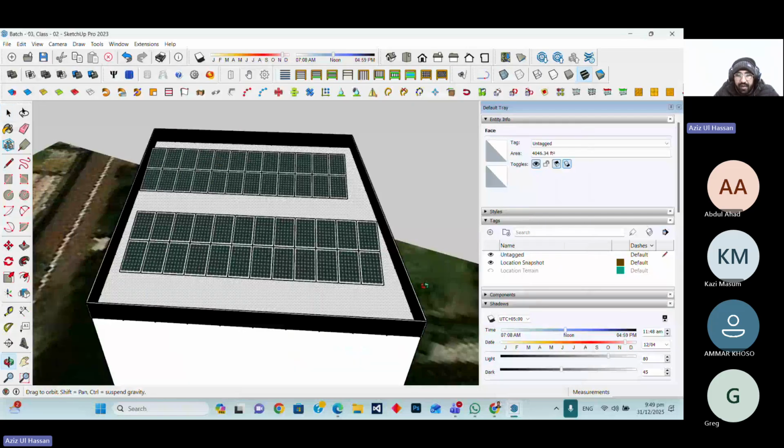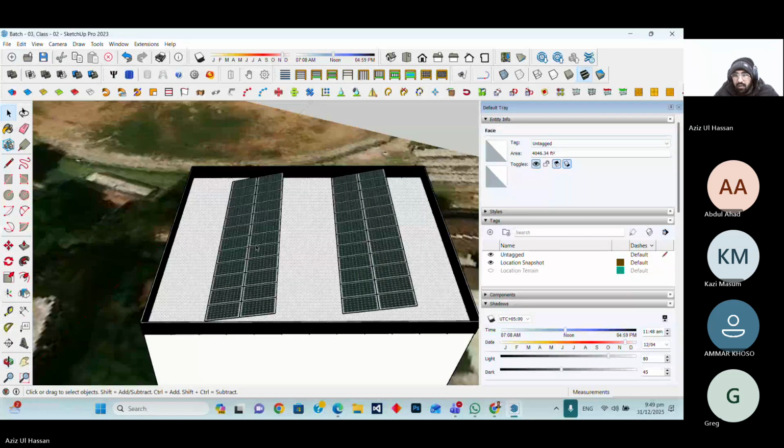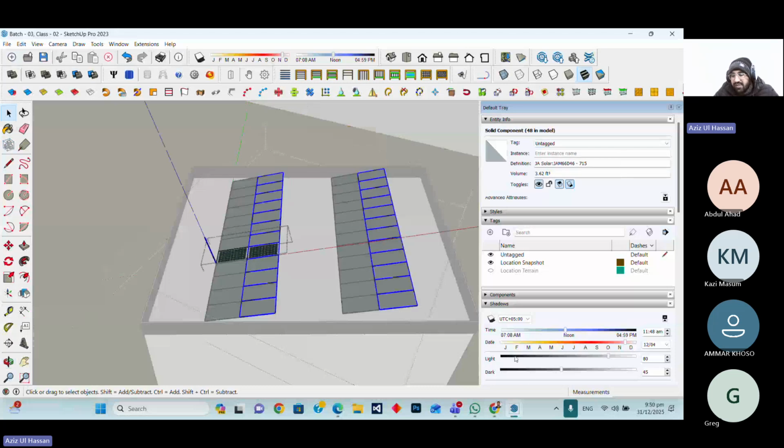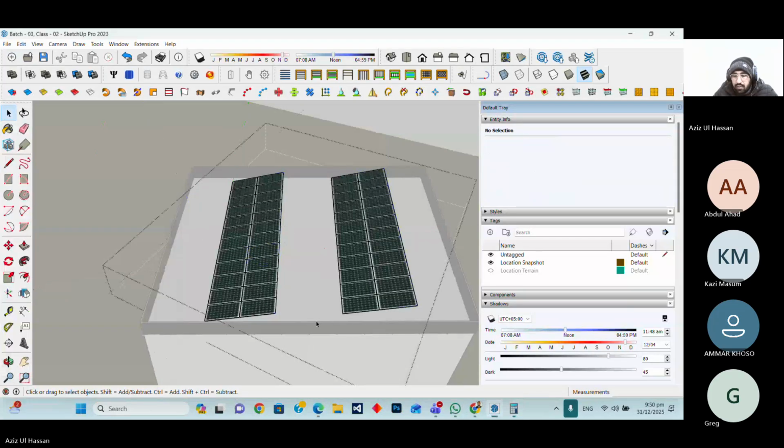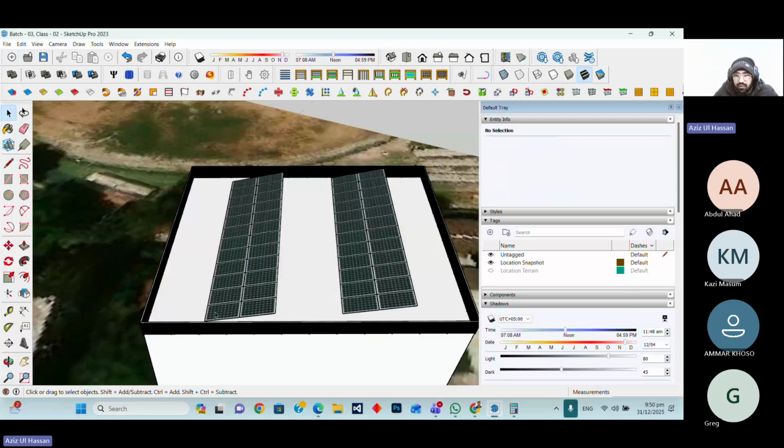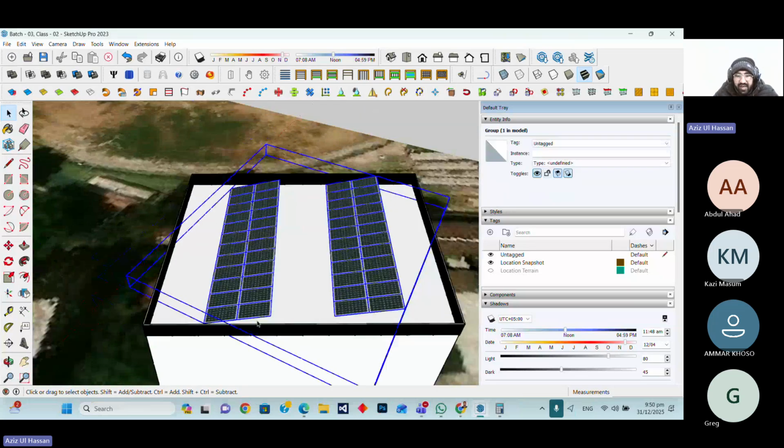They have made and installed the PV modules there. So what we will do, just click on that, check that it should be the 715 watt. So the 48 PV modules are installed. 48 multiplied by 715 watt should be, so it should be a 34 kilowatt system installed already. So we have to just adjust that option.